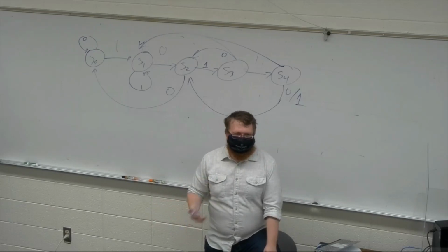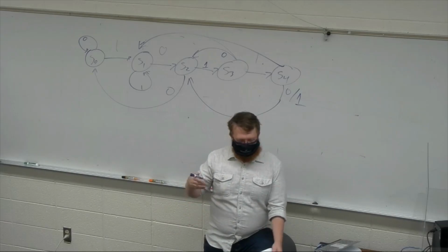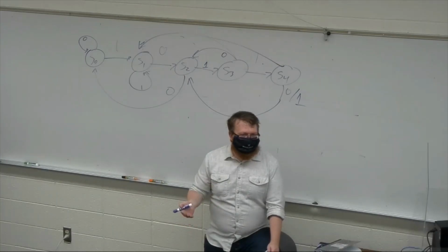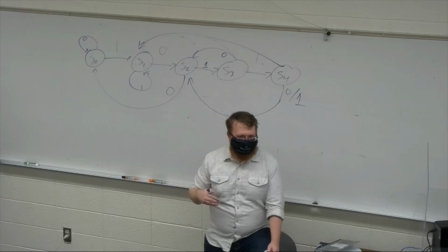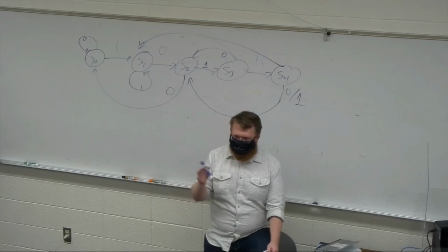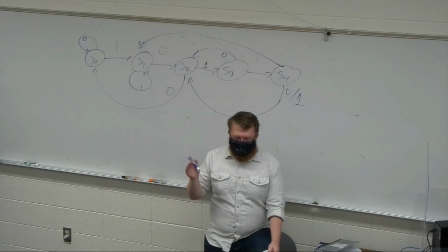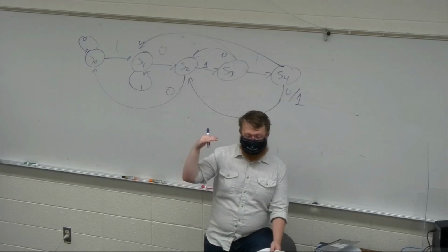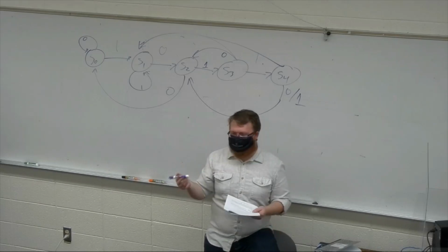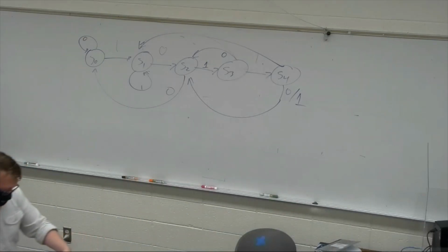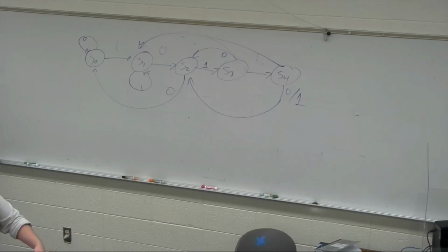A fair number of you got the points, so the requirement was basically that your flip-flop reacts correctly to the rising edge of X. I think that's what a lot of you guys missed, that X is the output of enable or clock. So as long as enable or clock is high, with a little bit of delay complexity in there, X stays high. So X just basically stayed high almost the whole time. There's only one opportunity, and I think I circled it on everybody's exams, and for those that don't have it, I will point it out, where you have not clock and enable.